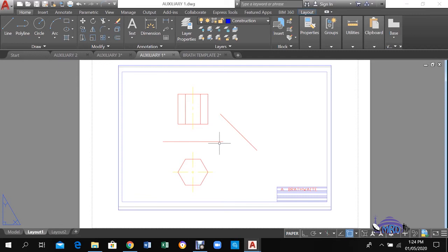And you imagine, for me please, that you're located somewhere down here, looking at this drawing, looking at this plan, and seeing what it would look like if you projected it up here. So your viewing area is no longer at right angles to the view, but it is at an angle. In this instance, we're using 45 degrees. So it is at a 45-degree angle, and that's the angle at which you would project your lines to do the construction.